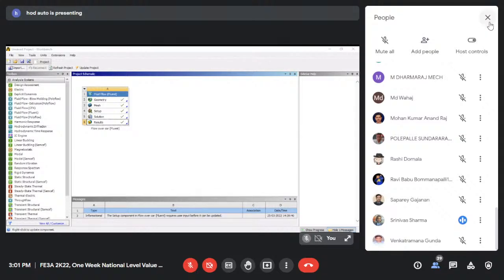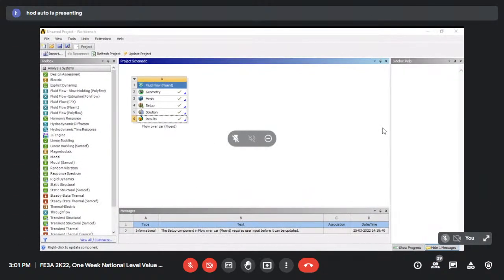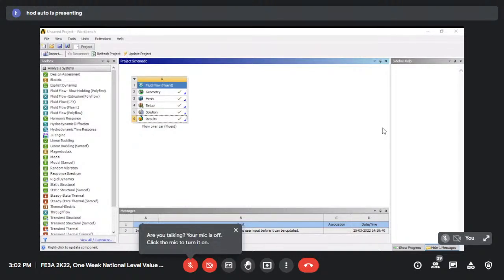Yeah, these are your post-processing solutions. If you are looking at it, this is my inlet of the wind tunnel. Now, I am interested to see visualization. Students, researchers, everybody wants visualization. Now, how is the fluid flowing? Because it is very difficult to understand the dynamics of the fluid. So I'll try to go with some streamlines. I'll ask it to put a streamline. Put a point 50.